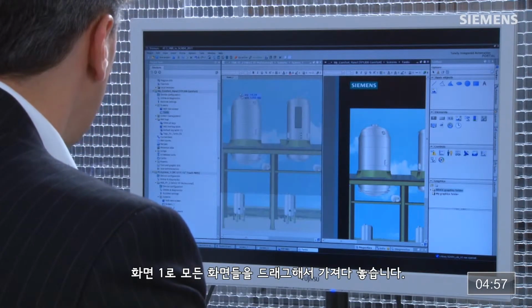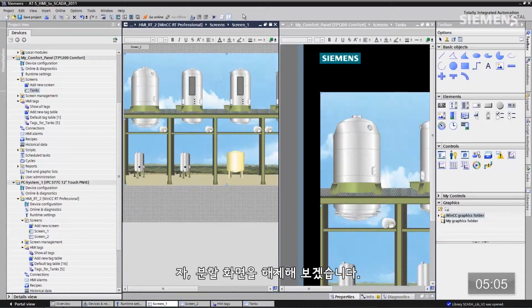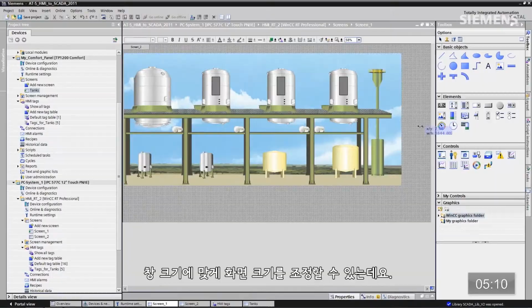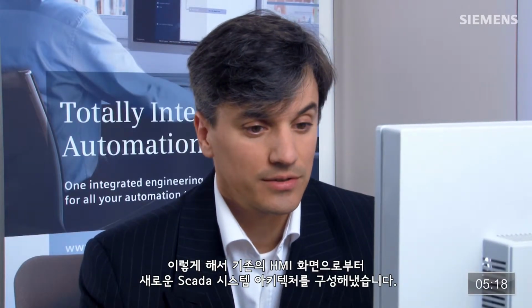Let's drag it up to screen 1. Let go. Guess what? We can do exactly that. We can reuse the entire screen. We don't have to create any of this code again. All right, let's click off the split screen. I can resize, refit it. Let's drag it over here. Now I've got my new current HMI screen in the new automation architecture of the SCADA system.